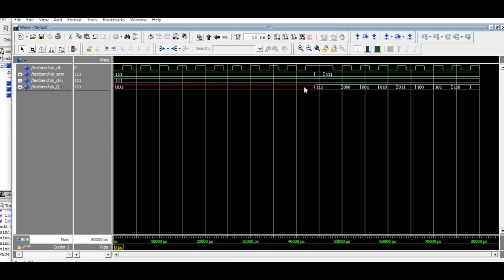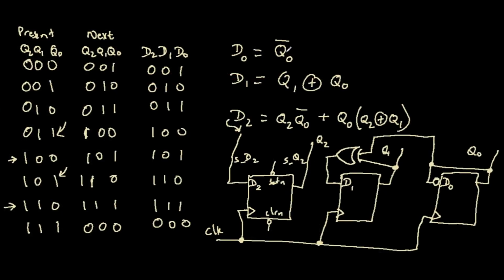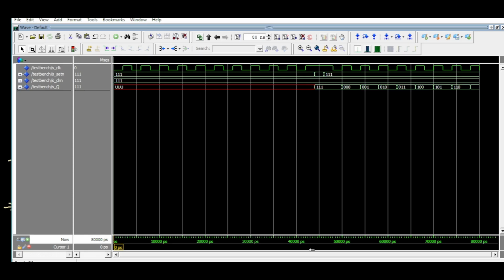It is uninitialized up until the point when we force the signal to go to 1, because if you have an uninitialized signal, if it does not know what the logic signal is, then when you have, say, not of Q0, for example, not of an unknown signal is an unknown signal. An unknown signal X is an unknown signal. So you always want to clear or set, or at least make sure you force your counter into a state you are sure of before you start using it. Take note of that. That's one thing that has shown up from this simulation.